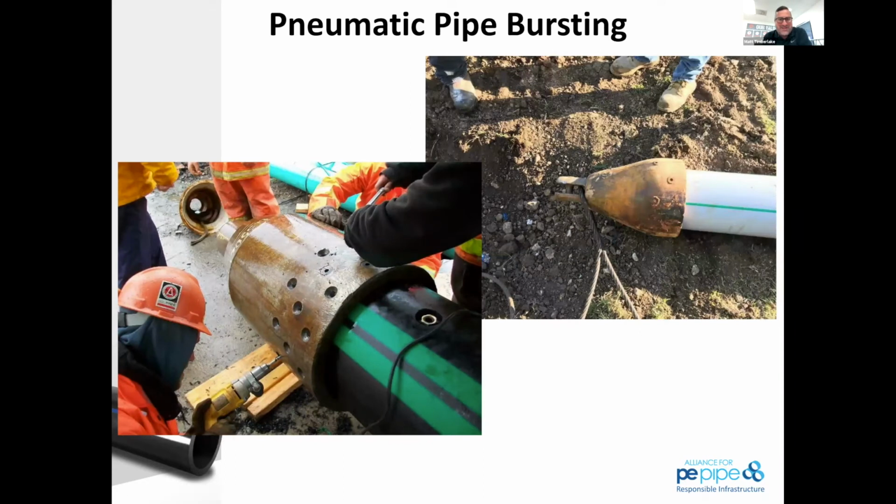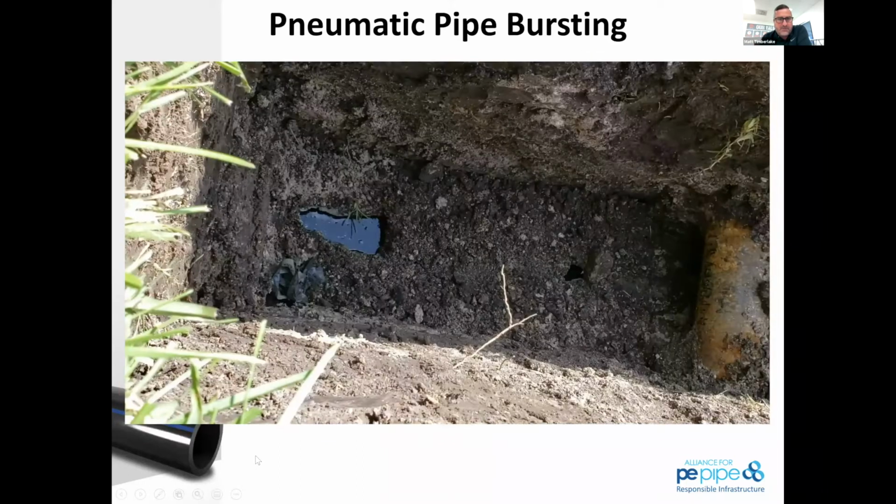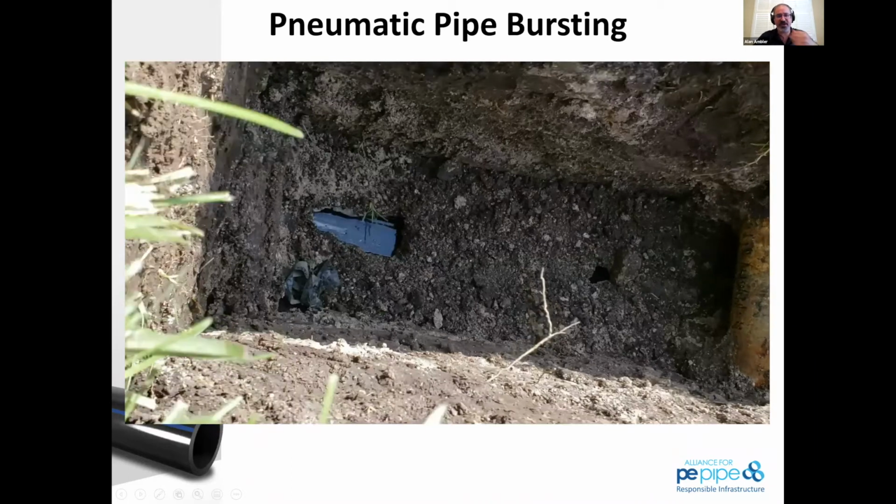The questions are coming in, which I like. So the photo on the left would show you a bigger pipe. That's a 16-inch pipe, and that has that same hammer that we looked at earlier, but it can be mounted up inside of the pipe. And then the picture to the right would be the head that would attach to that reversible tool. So when we land in the manhole, the only thing that's going to land in the manhole is that head you see in the right picture. The hammer is still up inside of there, but once we unhook the winch cable, we can just back the hammer out of our way and cut the head off.